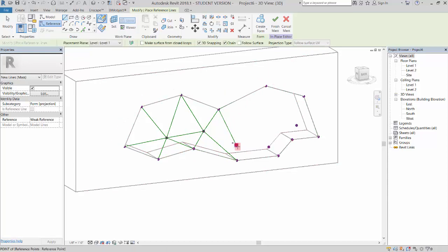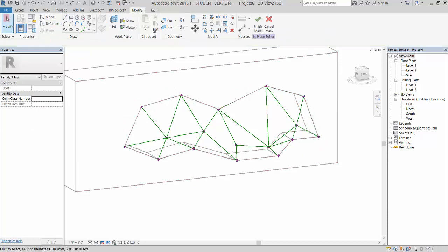The thing that is nice about having these points in the middle, I'll just leave that one curved. You don't have to have them all triangulated if you don't want to. So I'll leave a few that aren't triangulated just so you can see them. But you can just go in here and start clicking these things, right? So now we've got all those triangles, and now you go through and face each one of these. I'm going to face a couple of them, and then I'll pause and finish them off and show you what it looks like.